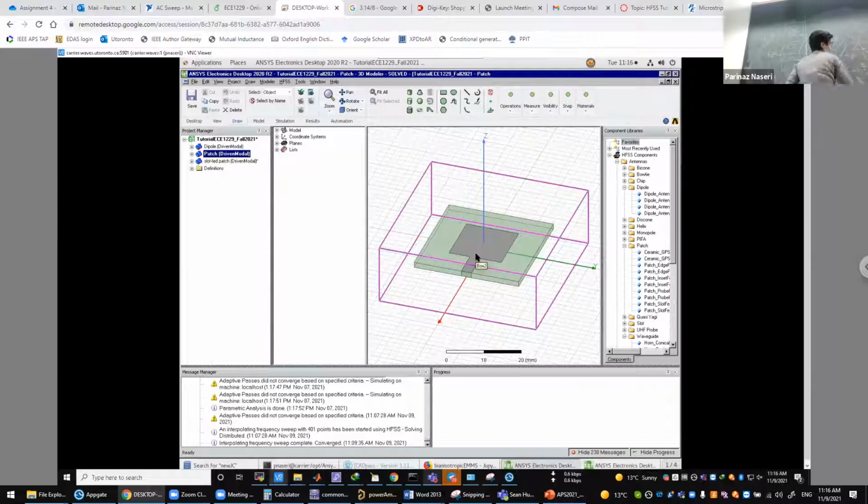To make the microstrip line go to the position that they want, they would make the shape like this. So they subtract these two rectangles from the patch so that the microstrip line exactly feeds the patch with an offset here, not at the edge. Again, this is exactly like tuning the position of this slot.